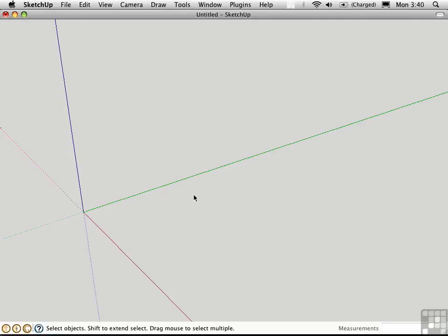Guides are a category of object in SketchUp. Guides differ from regular geometry in that you can't make faces with guides. Rather, they're used to aid in the process of drawing. Guides can be used to hold offset distances, angles, and points. To demonstrate this, let's draw a wall.